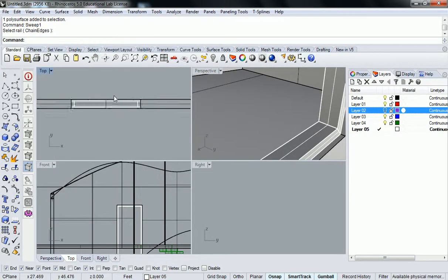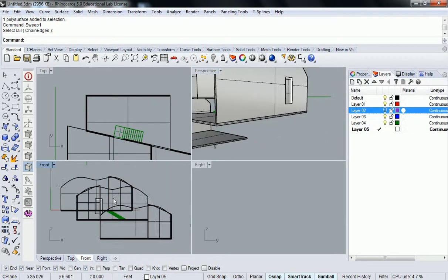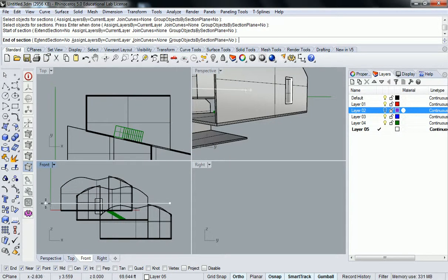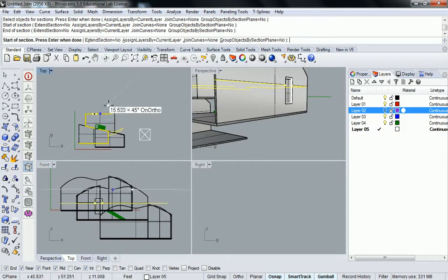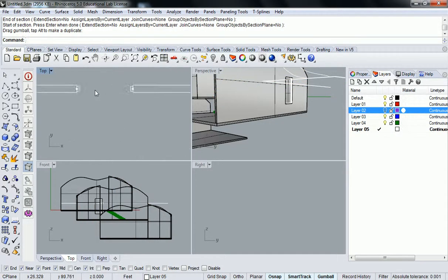So the important part of that I really want to get at is that if I do a section, right, this is the process for creating a floor plan. You select and you cut through the window. And then pull it out. And so the important part of that really is that now you have all of the line work right there. So if you have 8,000 windows in your model, all of it is already live, ready for you to cut. You don't have to edit it in AutoCAD in any way.